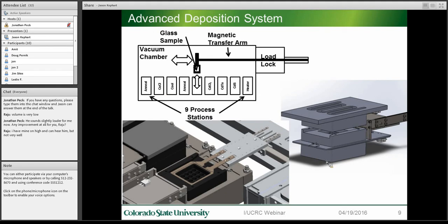Here you can see a model of our source, and it features a top and bottom graphite crucible with embedded resistive heaters. The bottom source can be filled with a sublimation material, and the top source helps control the substrate temperature. Both of these sources are controlled to a fraction of a degree C. When the end effector introduces the substrate into our source, the sublimation happens onto the glass as seen here, and the top is removed here for clarity.